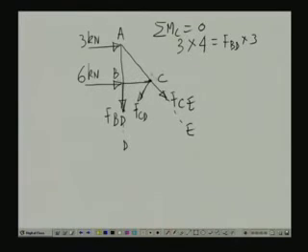This is an anti-clockwise moment. So FBD is thereby equal to 4 kilonewton. And again, at the joint it is in this direction, so in the member the force will be in this particular direction. So this gives us again a tensile pull. So this is a tensile force.